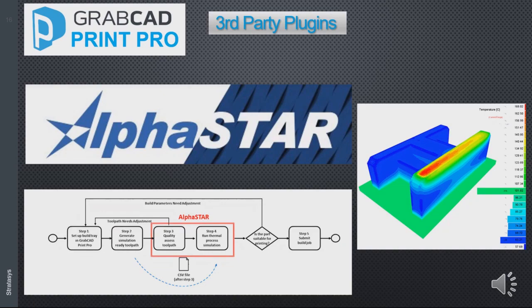AlphaStar is a simulation software that actually analyzes the build toolpaths that you generate in GrabCAD Print, and it will give you feedback on the thermal stability and thermal buildup within the part as it's going to be building, and any gaps that might be present within the toolpath parameters. So it'll analyze that for you after you've processed the job in GrabCAD, and it'll give you feedback on any probabilities of success or failure. And then you can rectify those by changing the settings back in GrabCAD Print and try again. So it'll actually predict failures in a build before they actually happen.